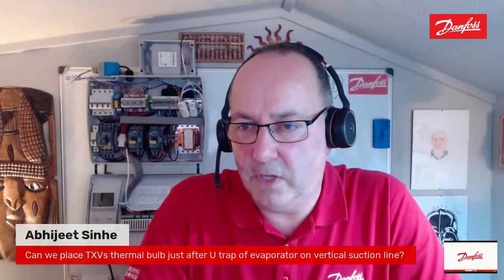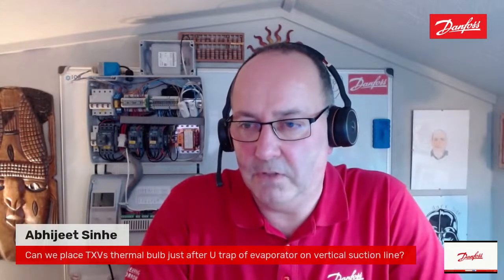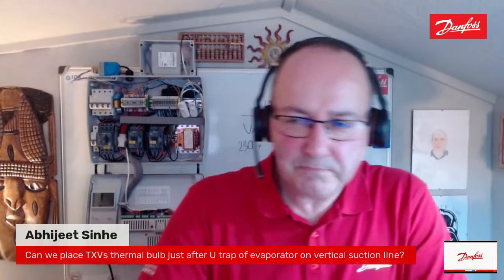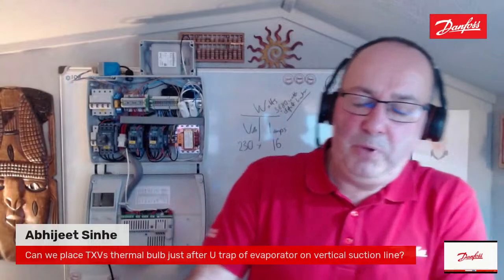We've got a question from Abhijat. Can we place the TXV thermal bulb just after a U-trap of the evaporator on a vertical suction line? Personally, I would always try and fit it before a U-trap, if you can, if you've got space.